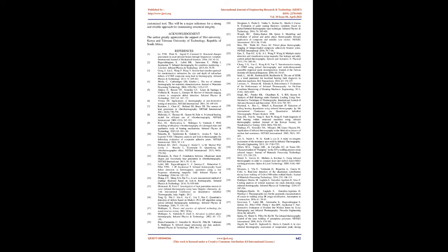In the case of beams excitation at different forcing frequencies, beam 1 at 20 and beam 2 at 40, the results revealed a frictional temperature increase of 0.24 and 0.32 in the former and latter, respectively, figure 10a. Authors found that frictional temperature evolution incredibly predicted the vibration frequency just like displacement curves, figure 10b. Also, they found the values to agree well with those corresponding to the forcing frequency. This implies that irrespective of the structural excitations, the analysis of the interface frictional heat evolution is capable enough of predicting its vibration frequency as evidenced by these findings.